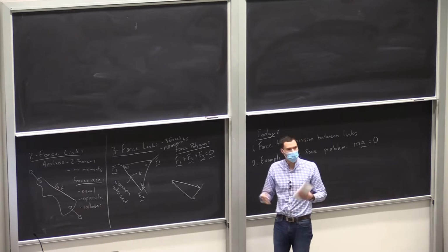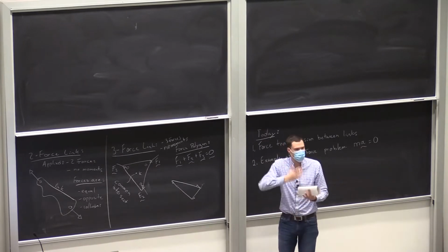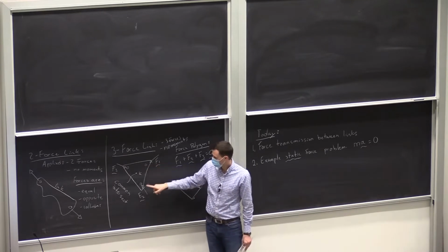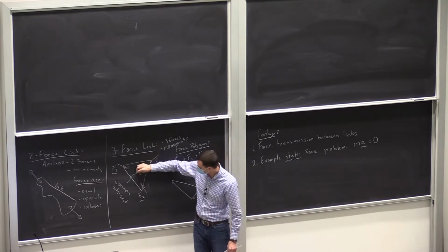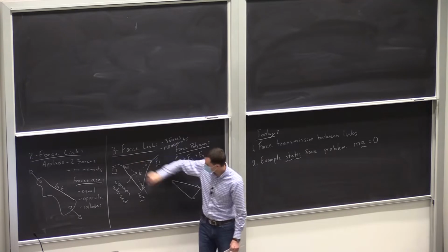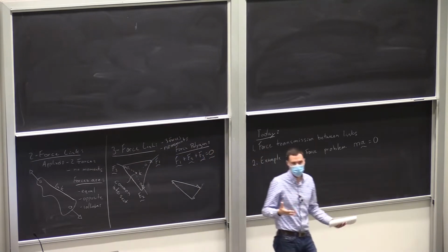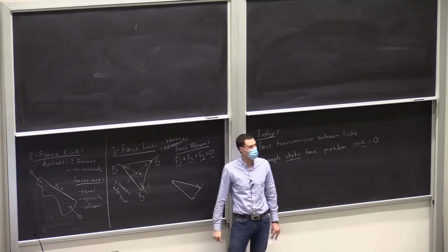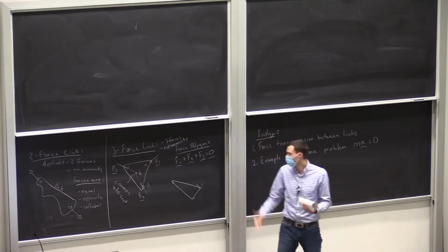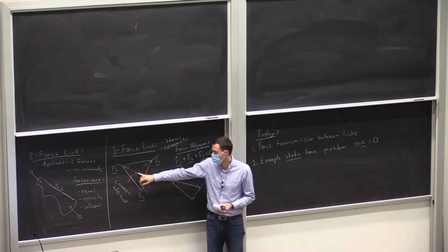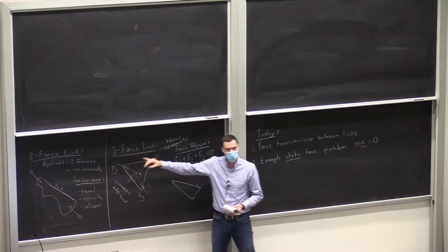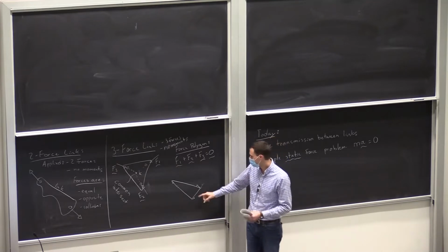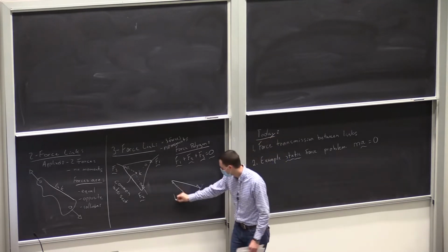Three-force links are a little more complex, but similarly, we just have a standard method of going through them. These three forces applied to our link all point towards a common location, and we called that K last time, this common intersection. These are the lines of action of those three forces, and they all point there. We solved a problem last time. We see how that point can solve for some unknowns, and then we do this thing called the force polygon to solve for the remaining unknowns.